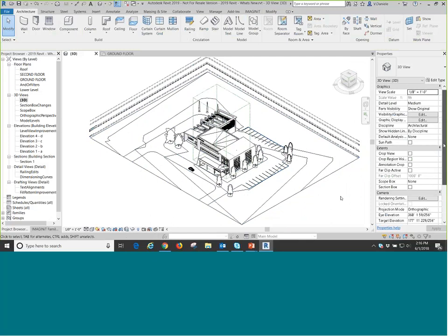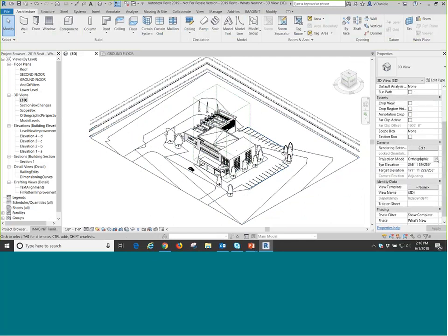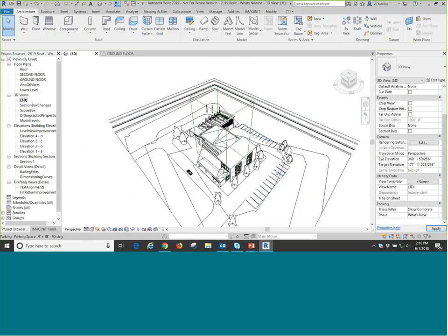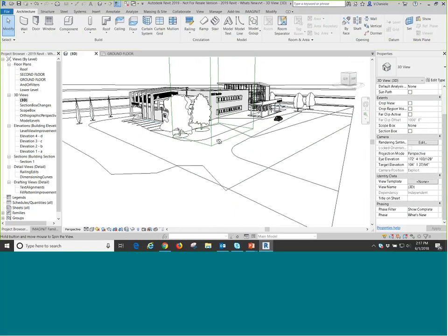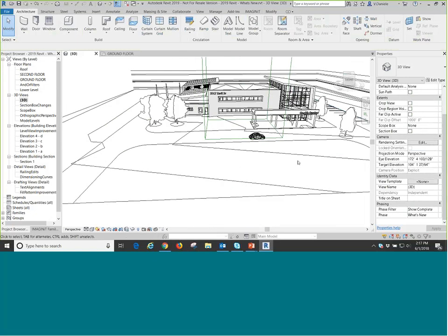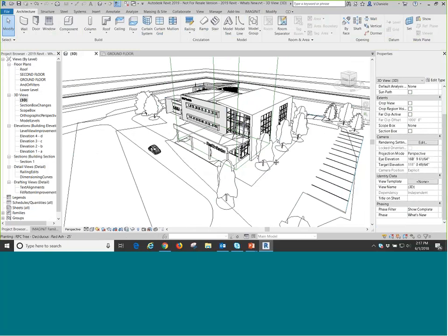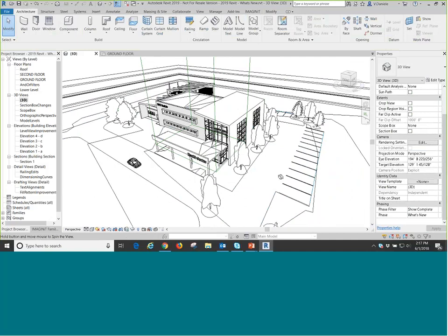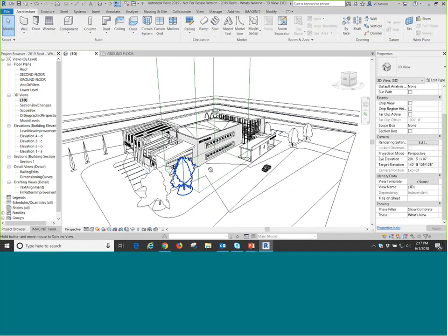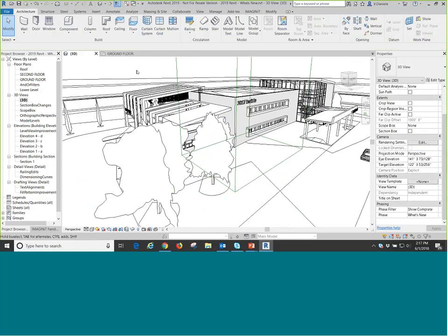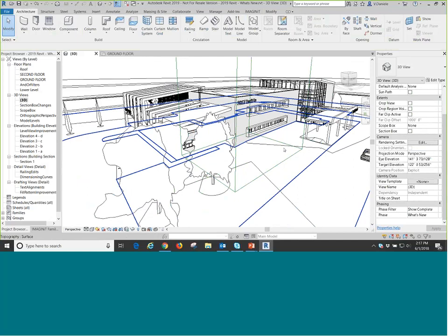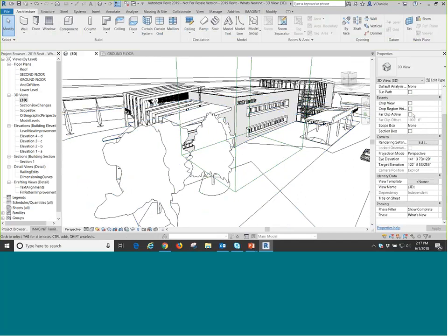While I'm in this 3D view, I might as well show you that we can toggle between orthographic and perspective. So it just changes your projection between orthographic and perspective. And another thing that's great, I really like this for visualizing our projects, is that instead of having your camera views or these new orthographic/perspective views cropped onto your crop region, you can actually display this full window. So as you're working through the views, you're not having to toggle between and mess around with your crop regions.